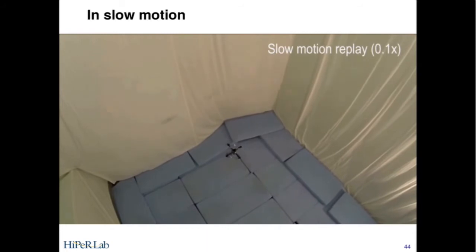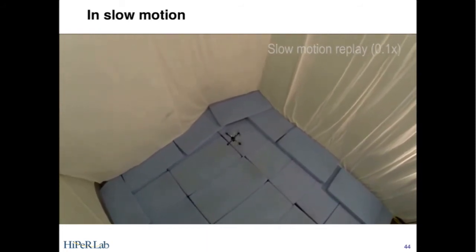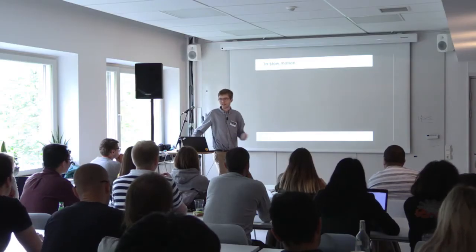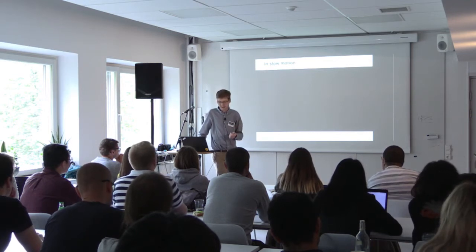And this means that you suddenly have a safer multicopter, right? Because you have a quadcopter, which we would have said is not safe because I need all four propellers to fly. And it's true, I need all four propellers to fly normally. But if I'm allowed to cheat and use this sort of relaxed definition of hovering, I can still fly if I lose one of my propellers.